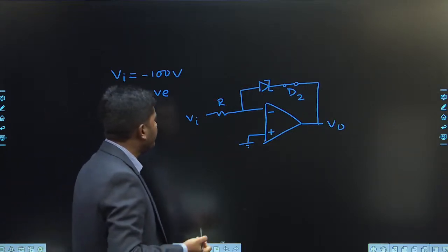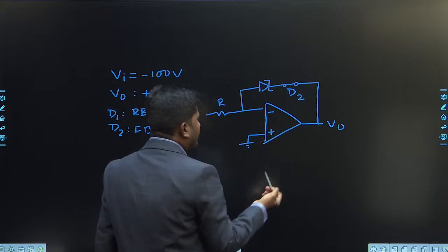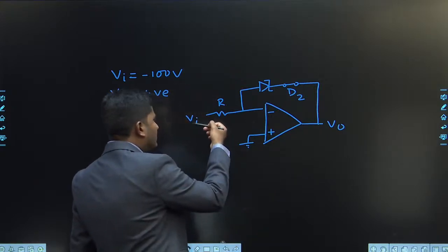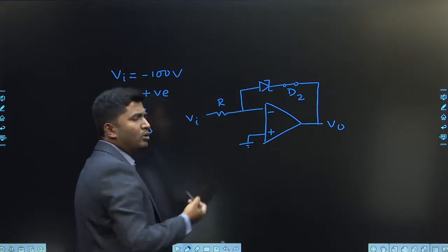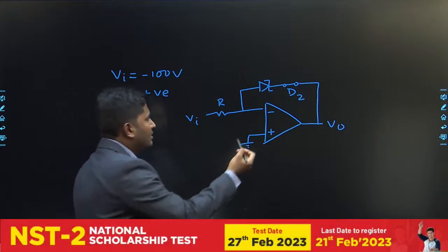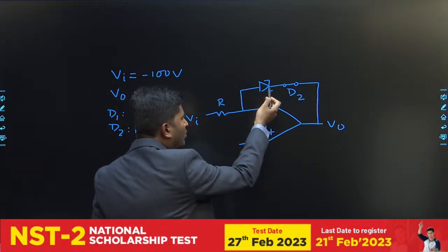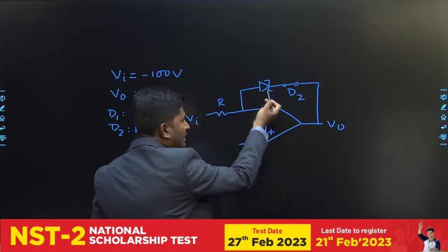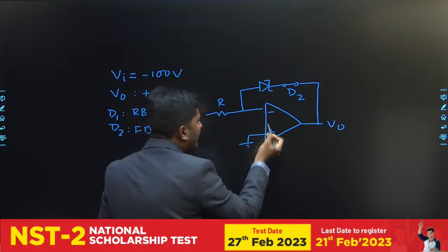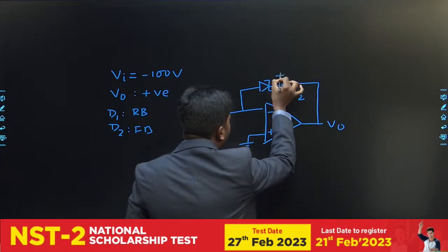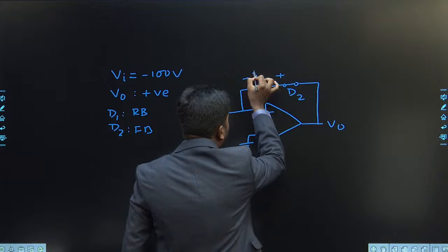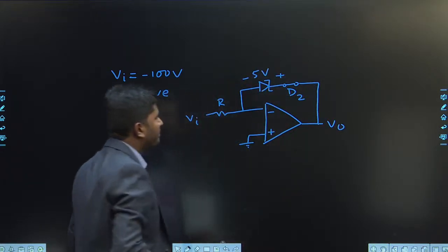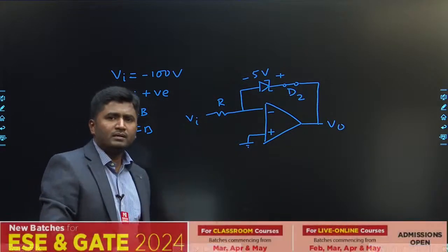output voltage. Now what happens here is, as we go on making input more and more negative, that Zener diode can go into breakdown also. If you have sufficiently 5 volt available here, then automatically Zener diode will go into breakdown. If the Zener diode goes into breakdown, across the Zener diode you will have a voltage of how much? 5 volt. I hope the point is understood.